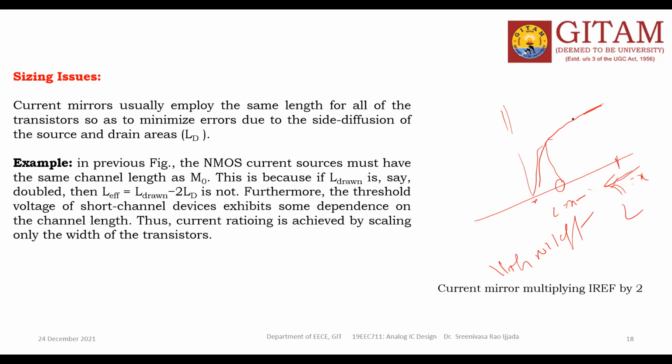Up to this point it stays more or less constant, which is manageable. But when L is decreased further, at a particular value of L, your VTH suddenly drops. What happens if VTH drops? Your subthreshold current is much more, because subthreshold or reverse current is exponentially related to the VTH value.